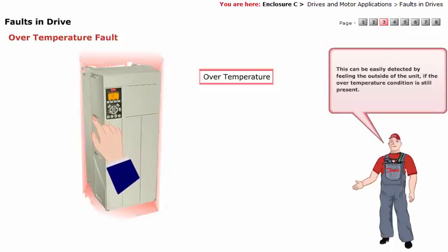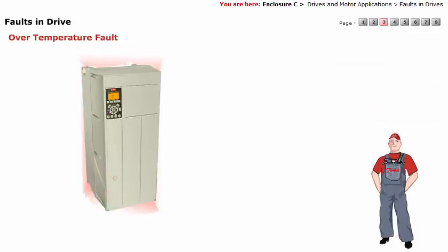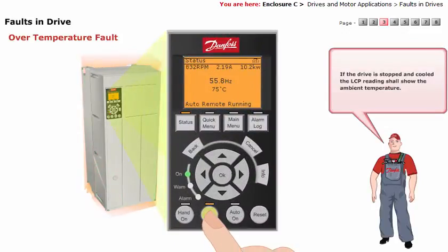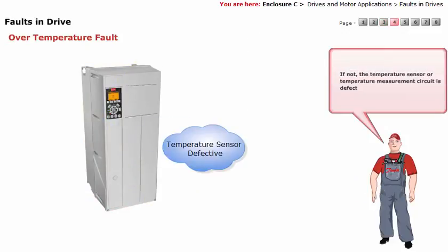This can be easily detected by feeling the outside of the unit to see if the overtemperature condition is still present. If the drive is stopped and cooled, the LCP reading shall show the ambient temperature. If not, the temperature sensor, or temperature measurement circuit, is defective.